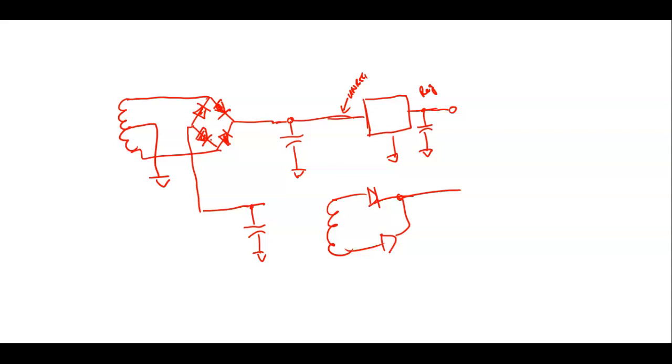These are voltage ratings, with varying inputs and also with varying loads over the design. So what does that mean? If I tried to get 500 milliamps out of that load, that Zener is going to go out of regulation because we designed it to handle the load between 2.5 and 7 milliamps.